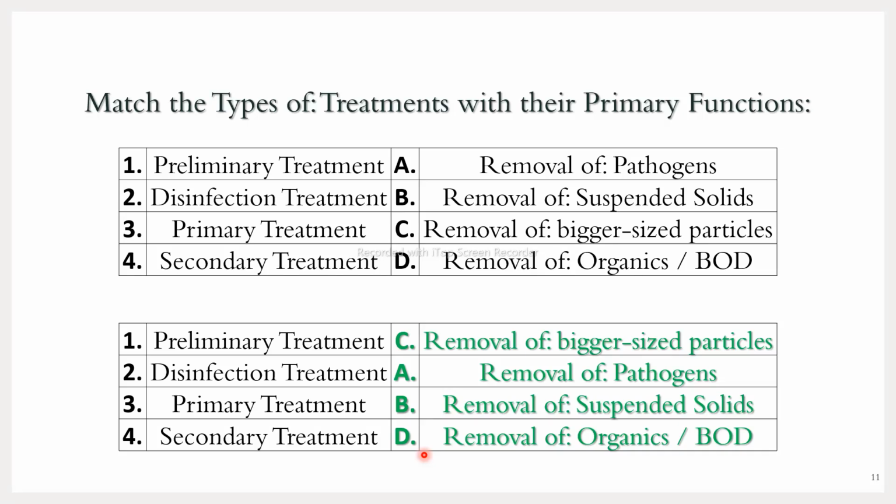If you keep the particle size in mind, then it will be easier for you to understand the treatment scheme if the preliminary, primary and secondary treatment schemes are all replaced with membrane. The membrane pore size is adjusted according to the particle size. We solved a problem regarding membrane treatment in the last class. If you watch the recording, you will be able to understand that.